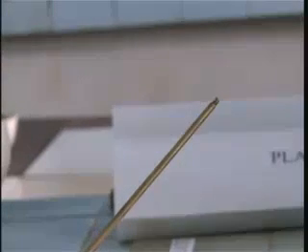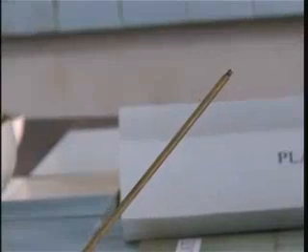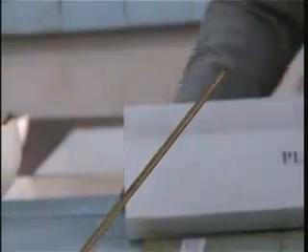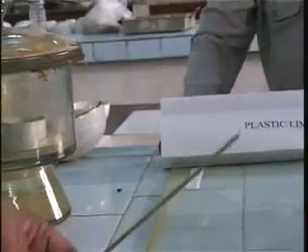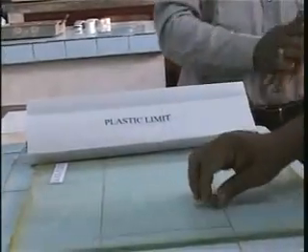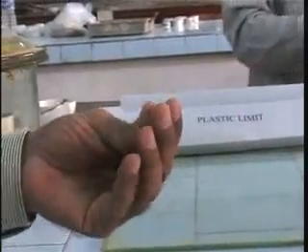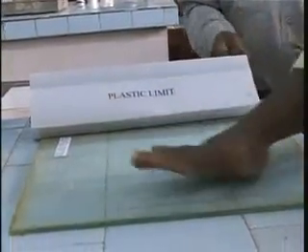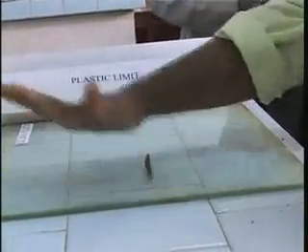And in fact, if the soil is at plastic limit, then it needs to just start cracking as soon as we reach 3 millimeter diameter. In fact, we won't be able to roll a thread which is finer than 3 millimeter size. So how do we roll a thread? That is being demonstrated by my colleague here, and this is the pat of the soil that we have here, and we just try to roll a thread by the procedure like that. And you can see that as the thread becomes finer and finer, it will have a greater likelihood of cracking.